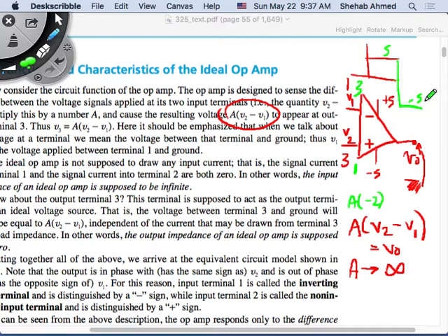This is not useful unless you're using it as a comparator, right? But we were not talking about comparators. We're talking about amplifiers, right? Amplifying a signal, amplifying current, amplifying voltage. So if that's the case, then I really don't want to use the op amp as it is. I would like to be able to figure out a way to make it useful. I don't want to just keep saturating my outputs to a supply rail or negative supply rail.